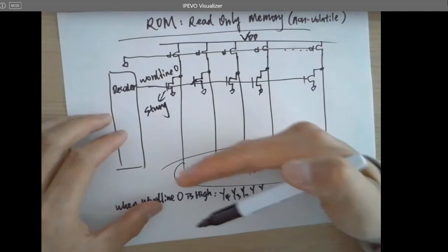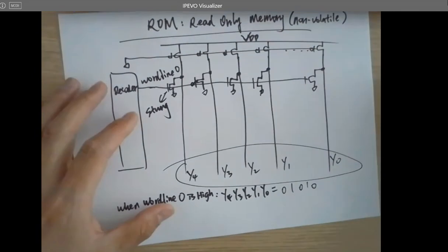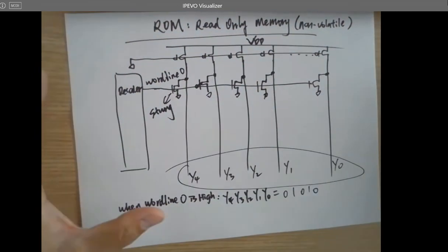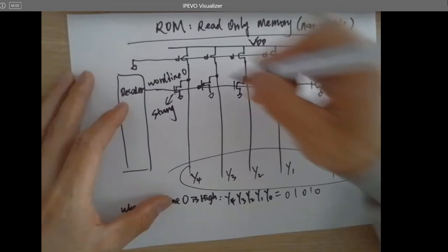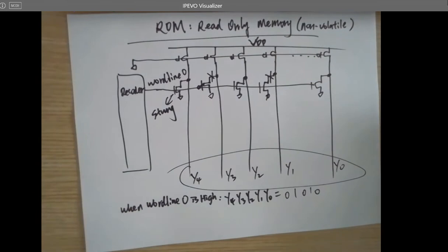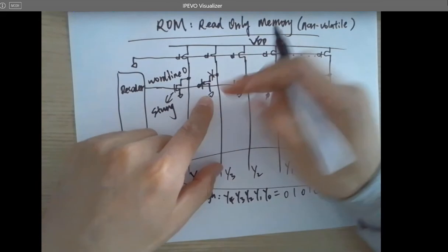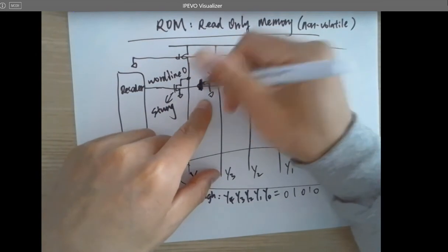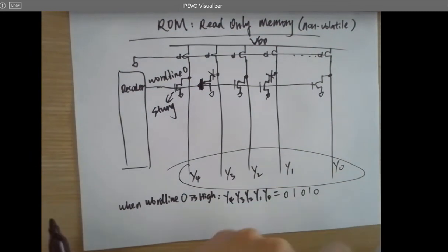It's just for every single row. And before they start trying to use it, they can program it using a laser. So under the microscope, they're going to use the laser to burn this wire to program it. Right? It burns it, just damages this NMOS, so it's not being shorted to this line anymore. So you can program a ROM.